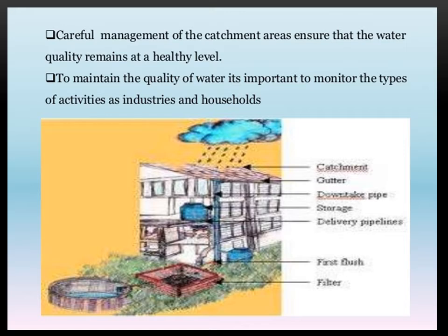Measures such as solid waste management, soil erosion management, and cleaning up of waterways are implemented to ensure the water collected in the reservoir is reasonably clean. Polluted water would require more purification before it is suitable for consumption. With careful management of the catchment areas, more water can be collected and less of it is wasted.